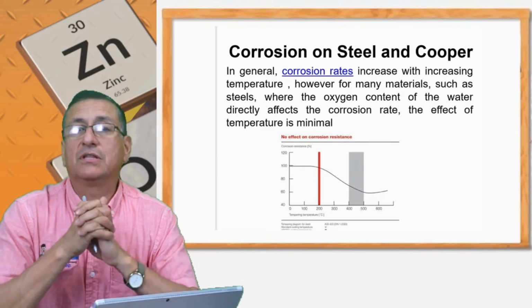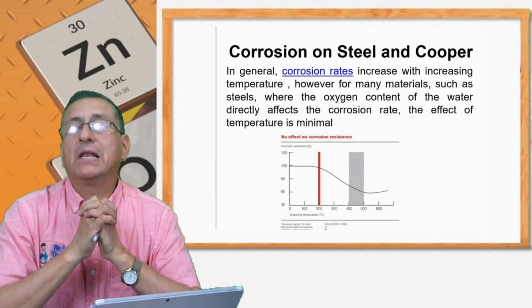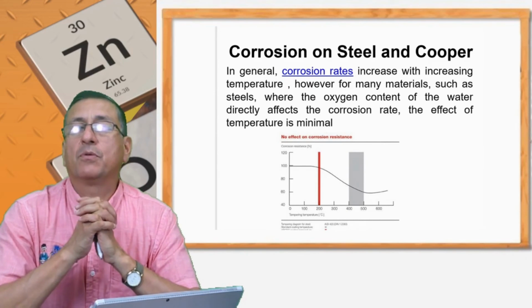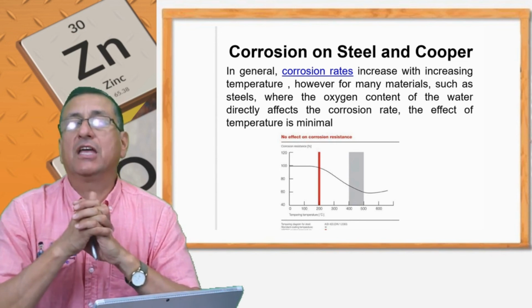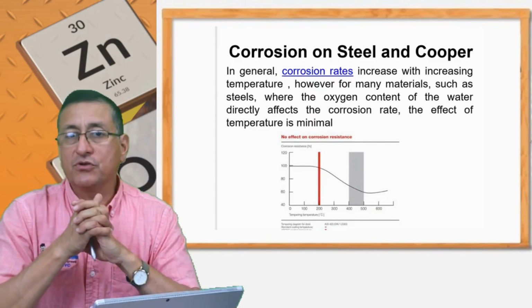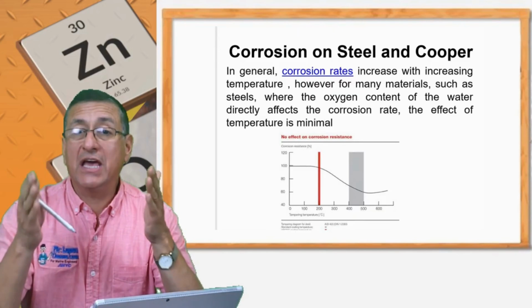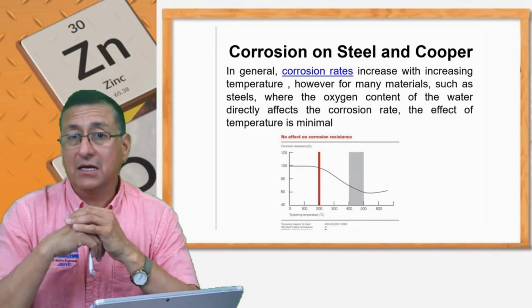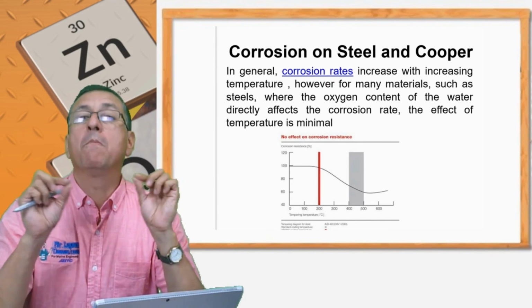Take in consideration that during the summer, if your boat is improperly protected, improperly bonded, not clean, or if the engine room is not dry, the process of corrosion is accelerated. This is the function of the engineer. Keep the boat clean, keep the boat dry internally, keep the boat properly bonded.